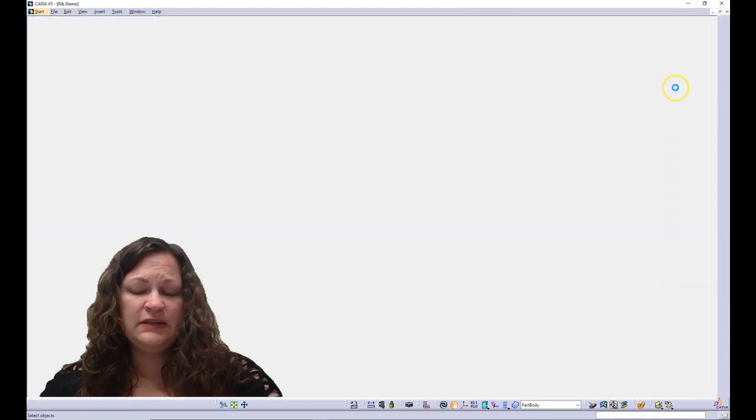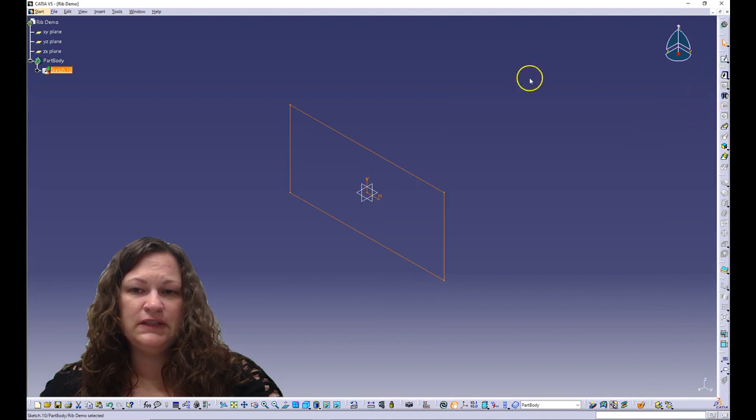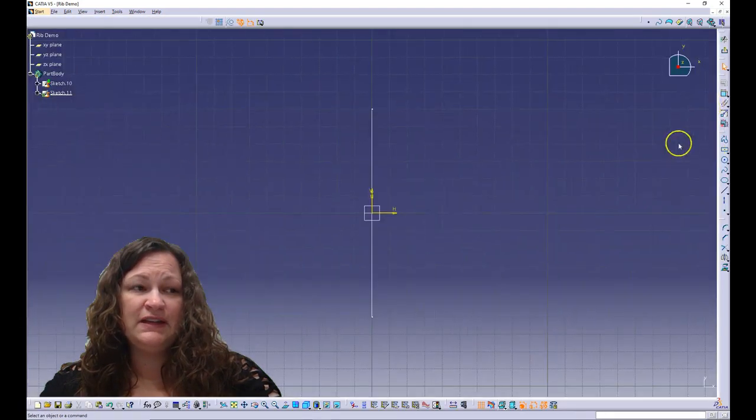And now I want to deselect my sketch and start fresh on a brand new sketch plane. So I want to choose one that's intersecting my profile. So that can either be my top plane or my side plane. In this case, I'm going to choose my top plane.